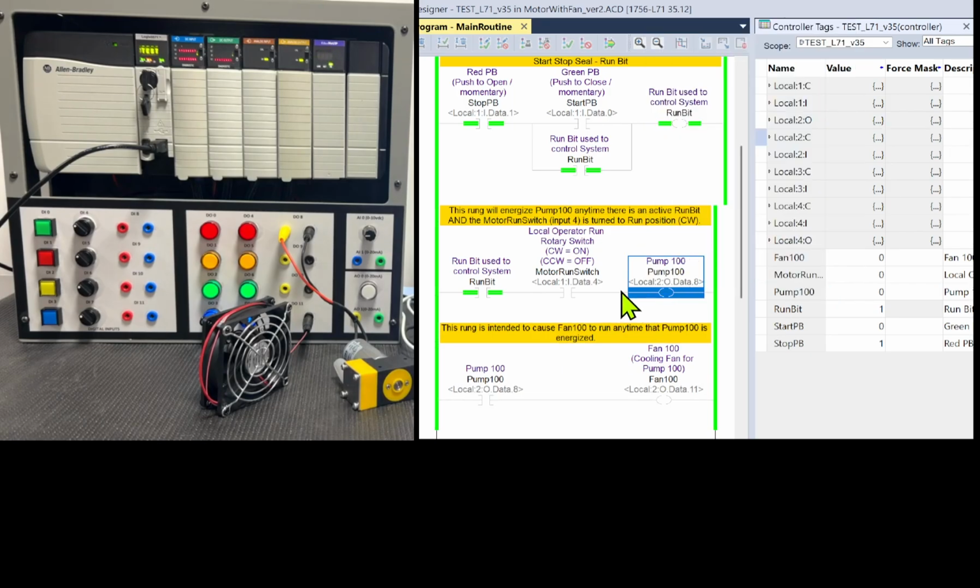And I'm going to talk about the different solutions here. Basically, the fact that you force an output will not cause any spots in that logic that look at it as an input condition to be true. It'll be whatever it is in logic. So the better solution would have been to force the real problem, which is the input. If the output's bad, you can't force it. If the input's bad, you can force it. Generally, it's much better to force inputs than outputs.